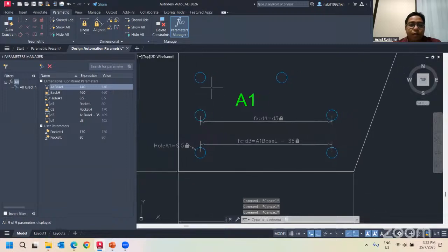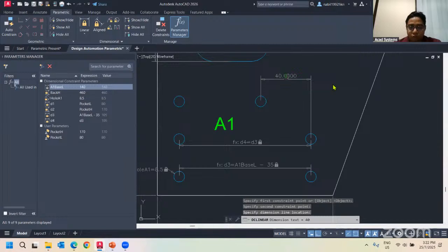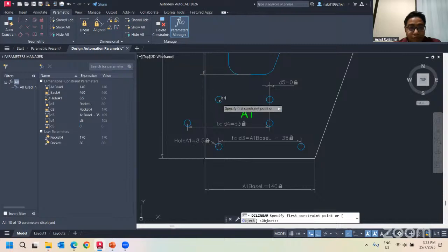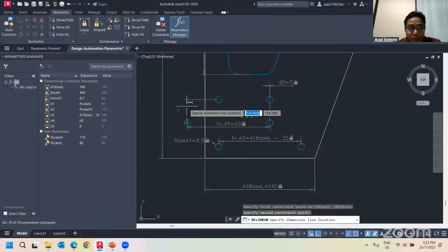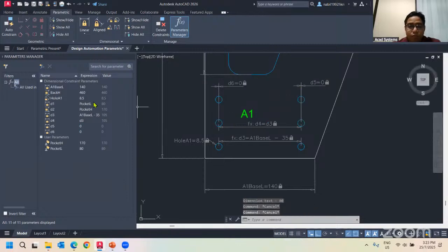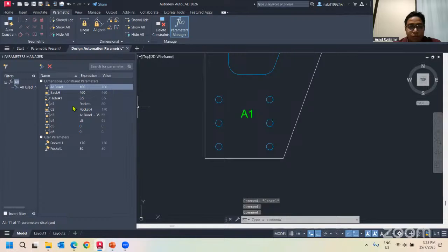The other way you can do it is to add a dimension from here and make sure that it becomes a line. I just put 0 over here, so it will always align with this. But I need to add some fixing over here first. Zero. Okay, so if I change it to 100, both will be changed.